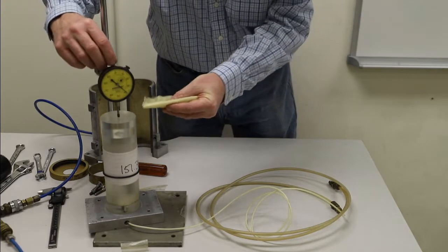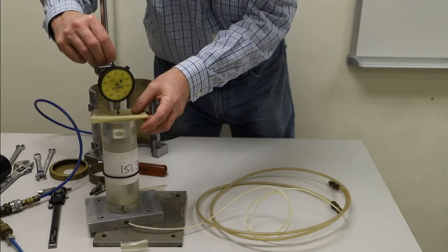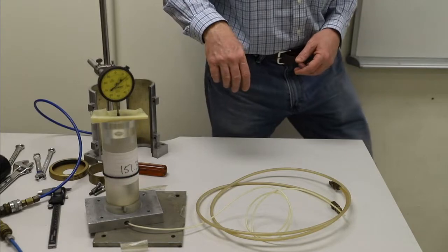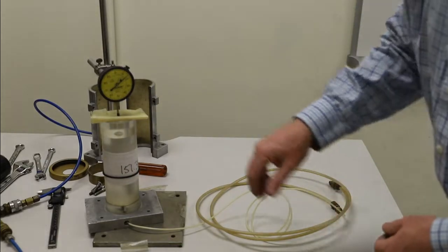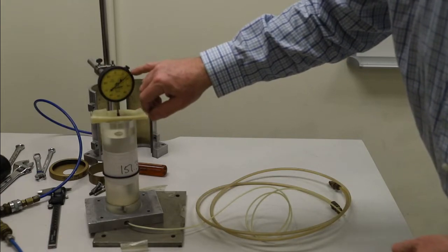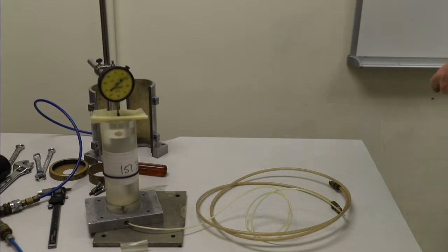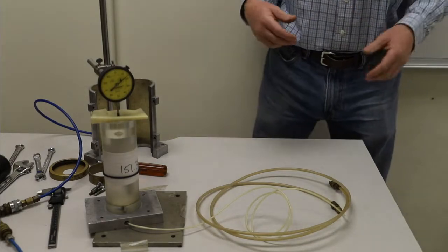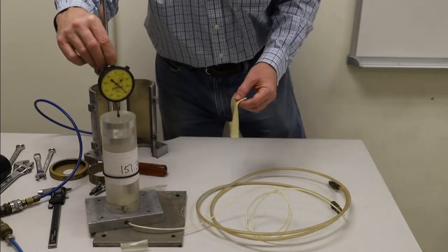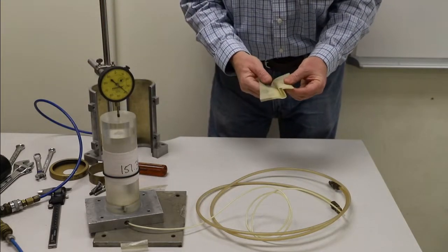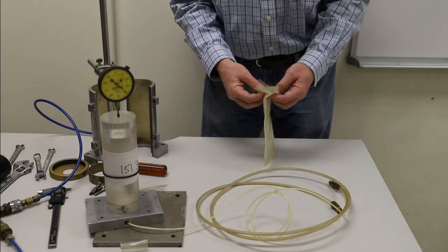And while the system is set up like this, it's convenient to just slide those 8 layers underneath the dial gauge. Now we have a different reading. Of course, the system is taller, so we can take this reading, subtract the 8.39, divide by 8, and that will give us a good measure of the average thickness of this latex membrane. There's a space on the data form for that. It should be filled out for you for your specimen.